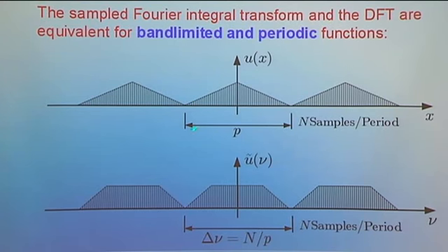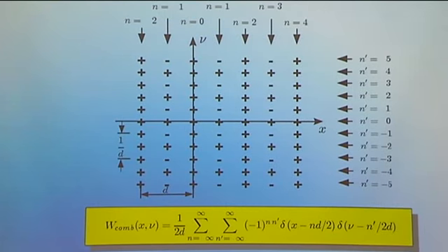And in this case, we really take sort of samples of the signal. We do not really mess around with a frequency band here. We just make sort of copies. So we can get our original function back very neatly by just low-pass filtering this. If we have a truncated non-periodic signal, we introduce some errors. But this is the model that helps us to understand where we are actually screwing up.